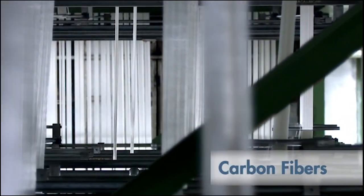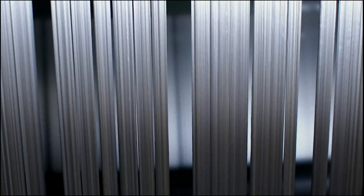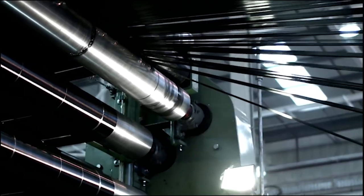The starting material for our lightweight, high-strength components is a precursor based on acrylic fibers. Complex oxidation and carbonization processes convert this precursor into carbon fiber, a unique material used in high-performance textile products and a wide variety of composite materials.